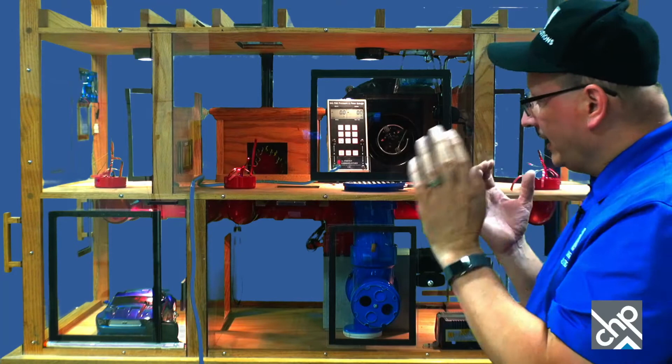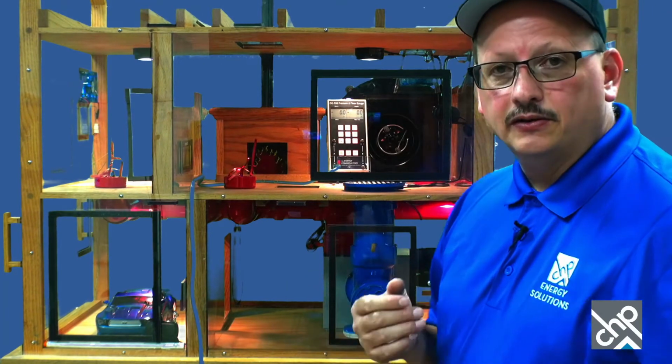So anyway, I showed you exhaust fans. So next thing we want to talk about is duct leakage. Duct leakage is very important, because if you have duct leaks, then you can be losing your heated and cooled air to the outdoors. You can be creating pressure problems, just like we talked about. It can cause problems from combustion safety, indoor air quality, durability, all those things. We mentioned efficiency. So duct leakage is your conditioned air.